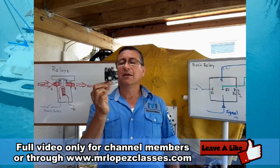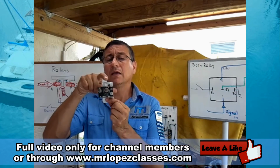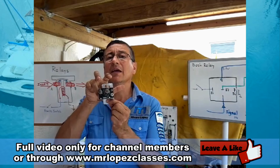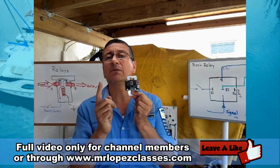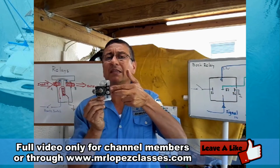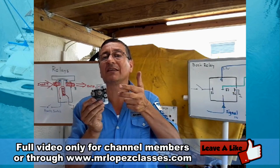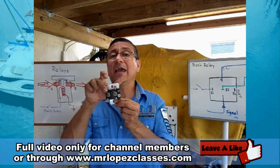What happens internally in the relay? Normally, terminal A, the bus of terminal A, is a copper metal, and terminal B, they are separated. But in between both of them, there is a piece of ferrous alloy, steel or iron alloy. That piece of metal between this terminal and this terminal is surrounded by a coil. The beginning and the end of the coil are those terminals. When you power that coil, the iron becomes a magnet and goes down and closes the gap between A and B. When you remove the power on the signal, the magnetic properties of the iron disappear and the iron separates, and A and B are separated.